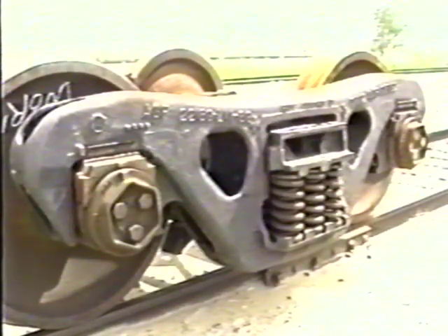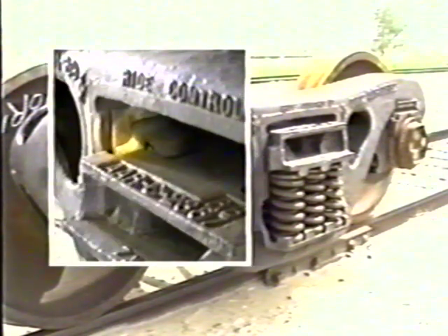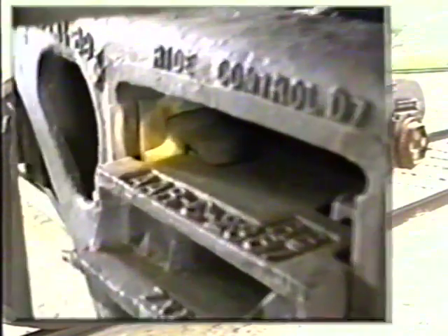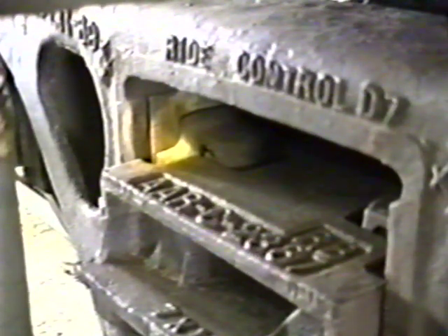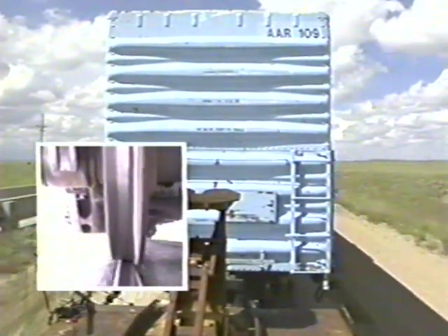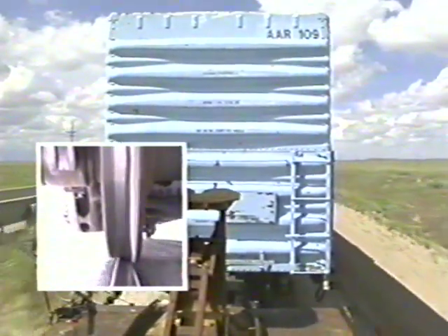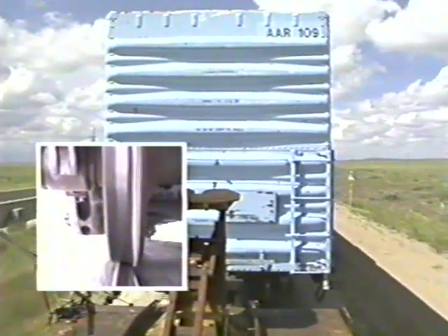In the rail car, undesired vertical motions are controlled by springs and snubbers. When operating over vertical track deviations, the snubbers control the rail car response. Worn friction wedges or faulty hydraulic shock absorbers will reduce the effectiveness of controlling vertical rail car response. To preserve control, it is important to maintain all snubbing devices and springs.